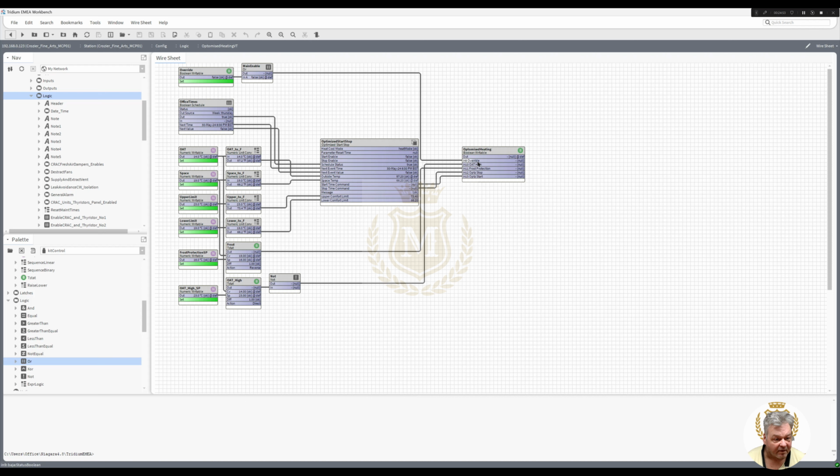So now you can see what I've used. That is your optimization done with high outside air set point, with frost protection for the space temperature, your lower and higher limit set. Your space temperature, which you would input there, and you've got 4 or 5 sensors. You put it to an average block, or you could put it to a minimum block. It's entirely up to you how you want to play with that one.